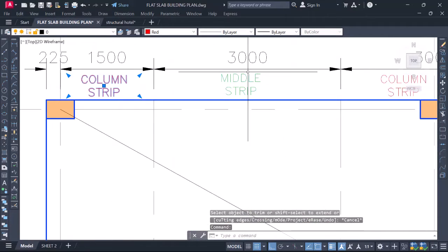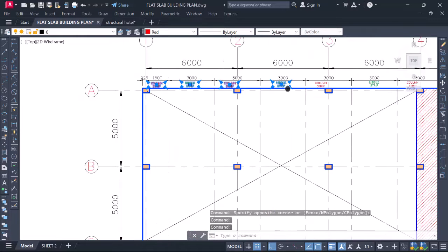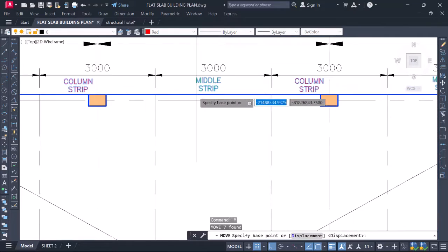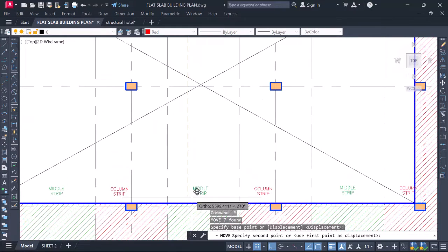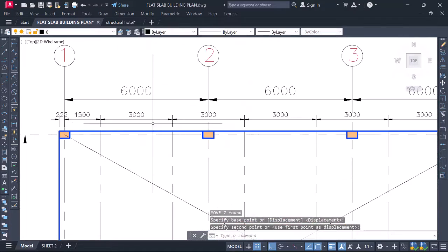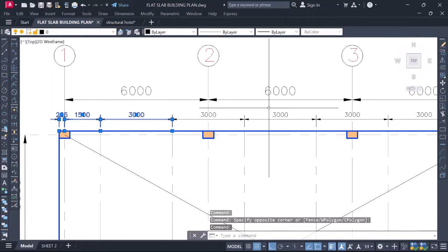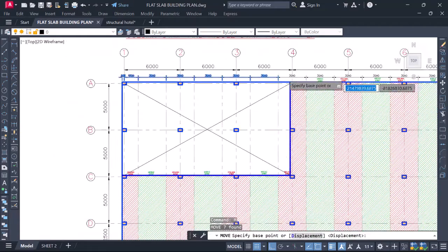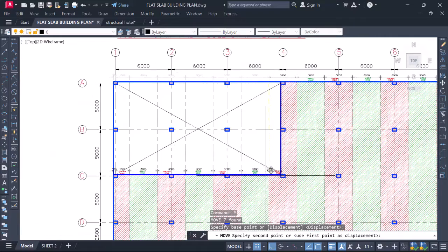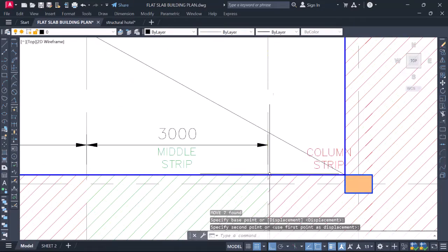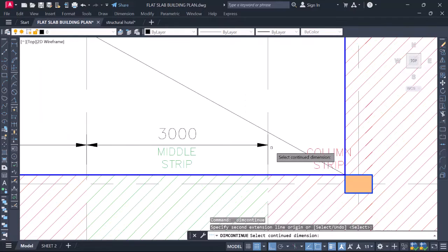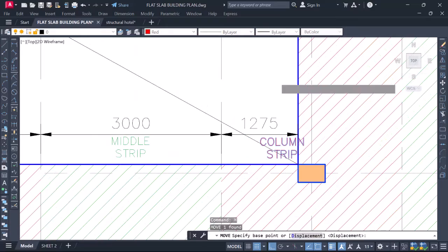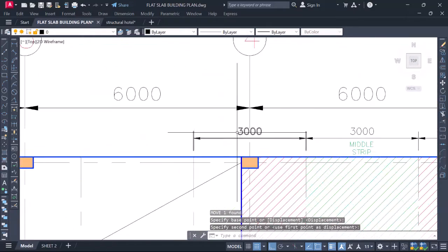And then I click on what? Escape, and then bring these ones downward. Okay, bring them downward now. Okay, here also and here. Move down, use your reference point, and then come down and click here. Perfect. And then come also and move these ones downward. Here, okay, and move. Use here as my reference point, and then come down now and place this here. Okay, and then continue dimensions from here all the way down here. So here move your backward column strip, and then adjust these dimensions.